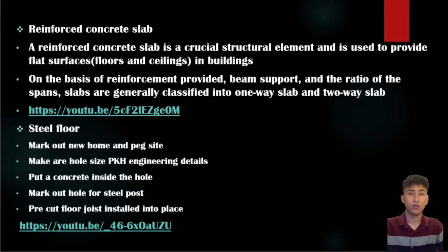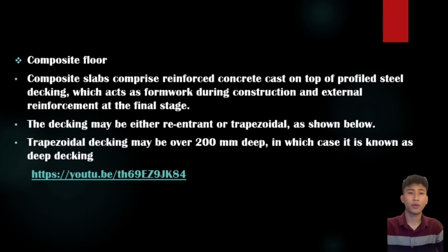Steel floor. Mark out new home and pack site. Make a hole size per engineering details. Put concrete inside the hole. Mark out hole for steel post. Pre-cut floor joists and install into place.